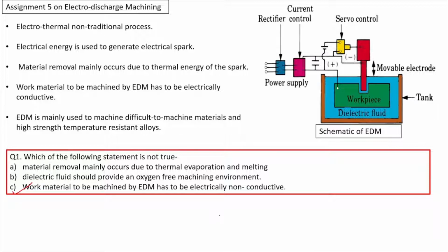The workpiece is made positive and the tool is negative, so that electrons strike the workpiece to form a crater due to the high temperature and melting. In this manner, material removal starts, and a constant voltage is not applied here. Only sparking is desired in EDM, rather than arcing. Arcing leads to localized material removal at a particular point. So here sparking is desirable.